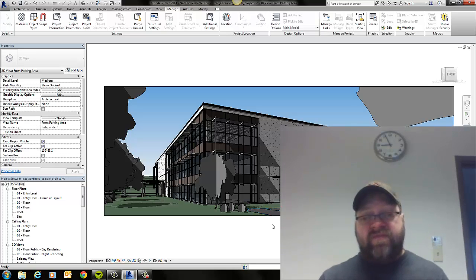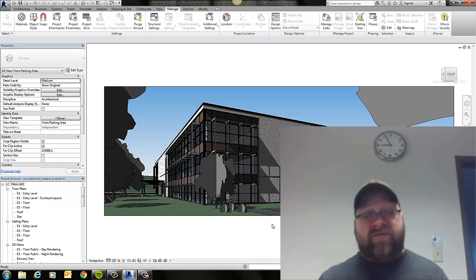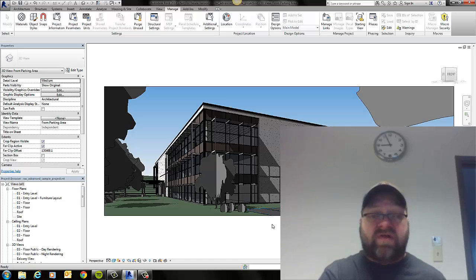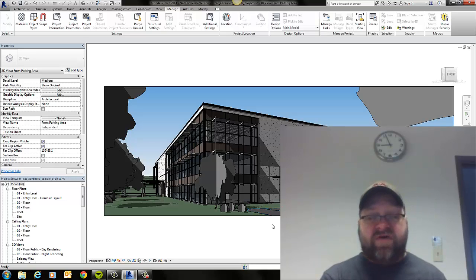So being able to group stuff in a way that's different is something that you can't do in Revit. For my example of existing, demolished, and new stuff, there's another method to handle that in Revit, which is maybe a little bit more complex than just throwing everything onto a layer. So that's another disadvantage of Revit: the category system, the organization system in Revit, has no real way to organize things that don't necessarily belong together.